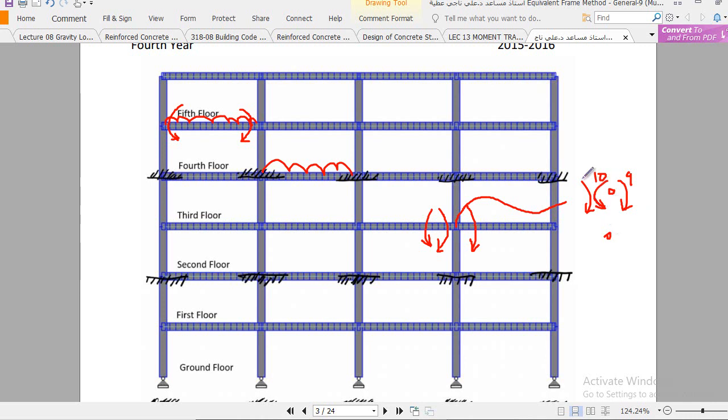And you see this one, let's say this is 2 kip-feet moment, so this one and this one will be added up because the direction is the same. So this will be 11, and 11 minus 10 will give you 1 kip-feet. As this clockwise moment is dominant, the net moment will be clockwise, and it will be 1 kip-feet.